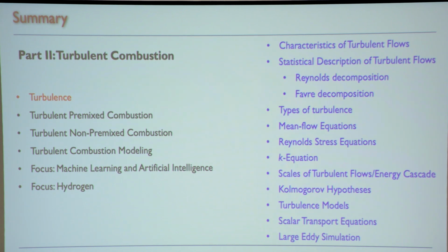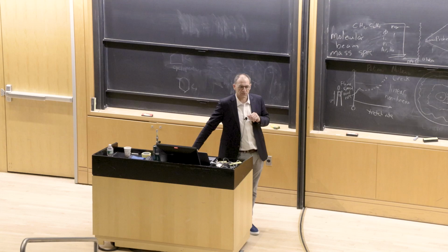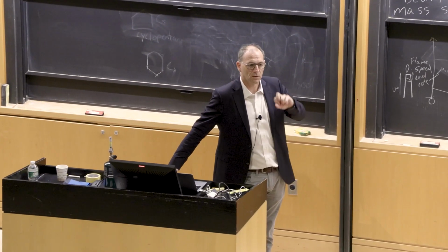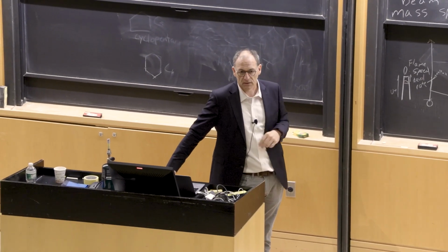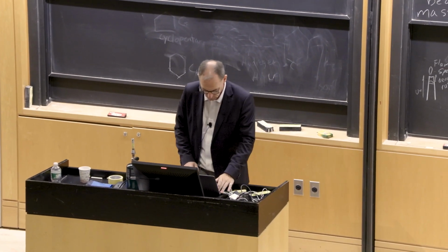One more thing for large eddy simulation: because you filter out only a very small part of the turbulence, usually the viscous terms that we always neglected when we talked about RANS cannot be neglected in LES. So keep that in mind when you ever want to do LES.